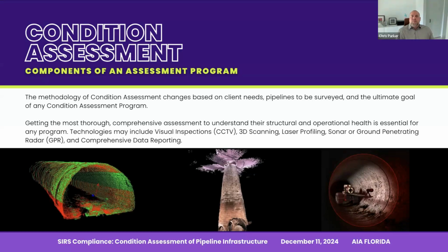3D scanning, which helps give ovality of the pipeline to make sure it's structurally sound, that it's round if it's supposed to be round. And then from there, you can correlate that into further data. Same thing for sonar. If you have pipes within a building structure, or substructure rather, that are constantly underwater, you still need to understand the overall condition of that pipe, but you also need to understand what that debris field is like inside of that water line.